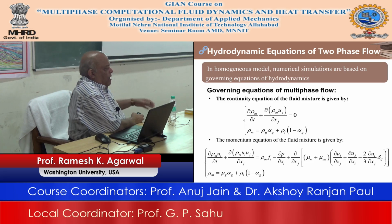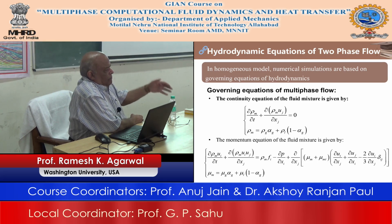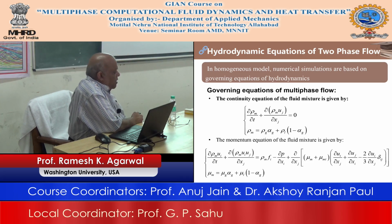But otherwise, you just take the solver and say I am going to use the VOF, and you put in the condition, that is how you put in a flag that there will be an air pocket in this grid when P is less than PV, and then automatically Fluent will change it to an air pocket. It has been applied by people, Fluent has been used, but I am just giving you the mechanics of how you use Fluent.